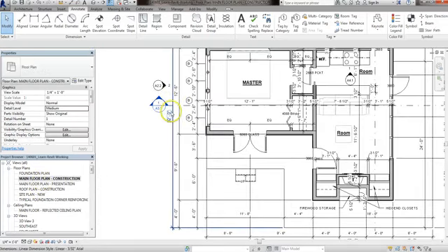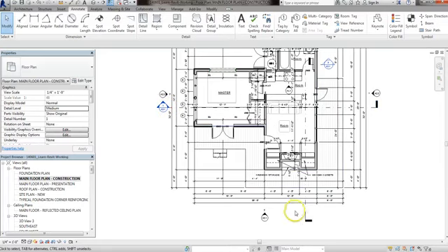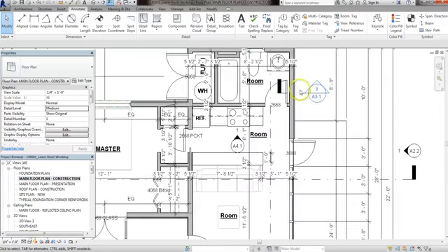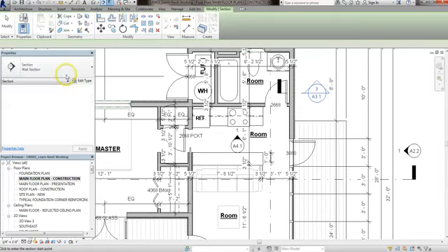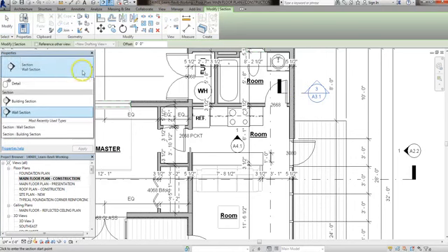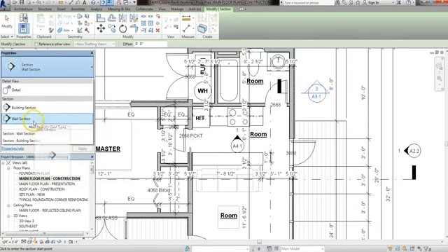So these are called building sections because they cut through the whole building. Wall sections, and under Views, Sections, to create this, the first one that popped up is Building, Wall, and you can change it from Building to Wall Section, just like any other component.